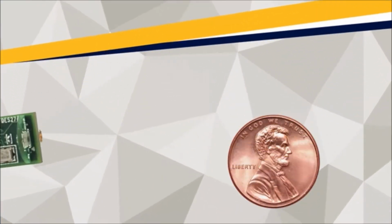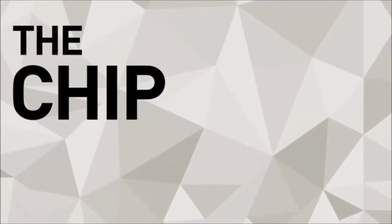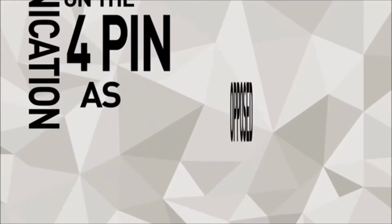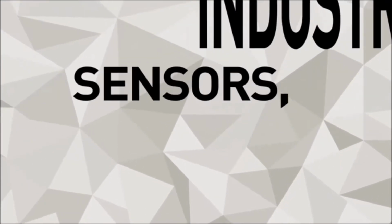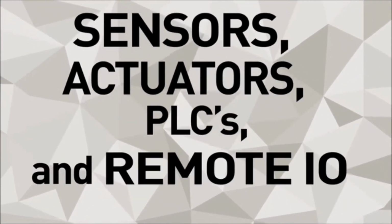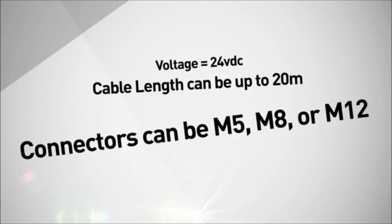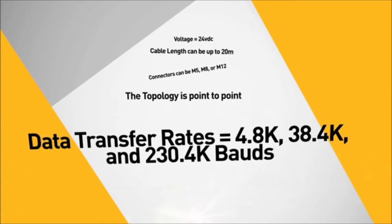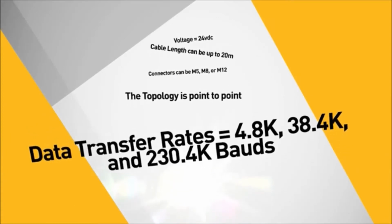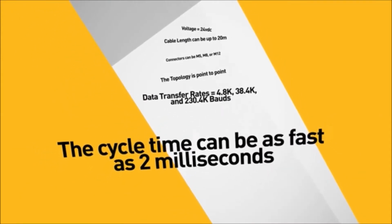From a hardware standpoint, I/O Link is just a chip, shown next to a penny to show the size of the chip. The chip allows communication on the 4-pin as opposed to an on-off like a traditional sensor switch. Applications include industrial sensors, actuators, PLCs, and remote I/O. Voltage equals 24 VDC. Cable length can be up to 20 meters. Connectors can be M5, M8, or M12. The topology is point-to-point. Data transfer rates equal 4.8K, 38.4K, and 230.4K bauds. The cycle time can be as fast as 2 milliseconds.